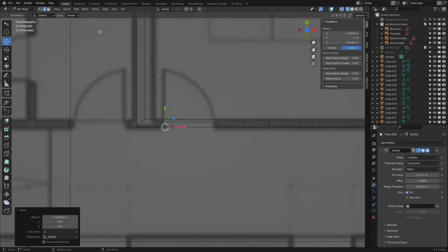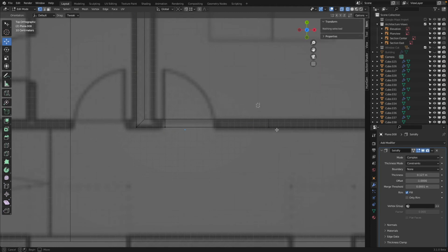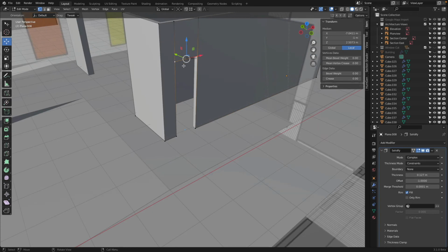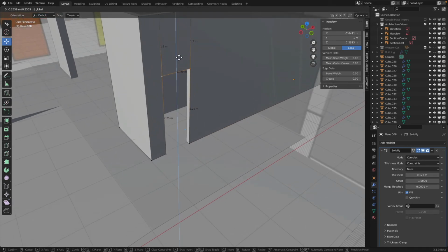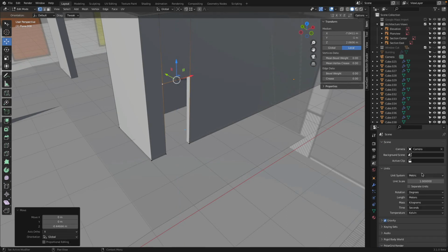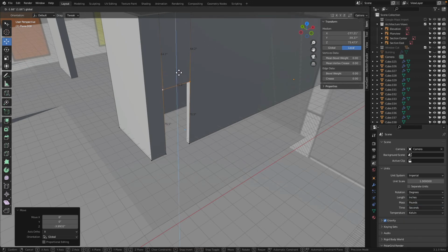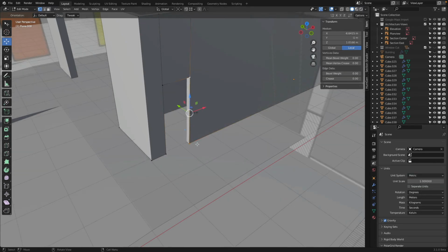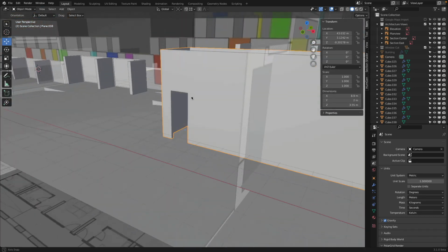Can bring this one to there. Point select A, B. Bring this to there. There would now be the door. What's the height? When I move this one down there, you can see there's the readout. We can quickly change this maybe to imperial. So this should then, no, not feet. Show me inches. Let's maybe go 80 inches as a reference. So 2 meters something. Okay.